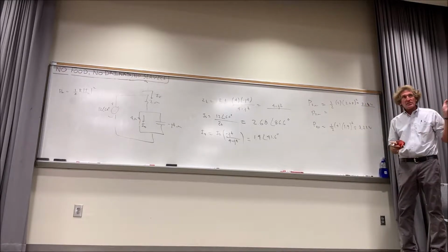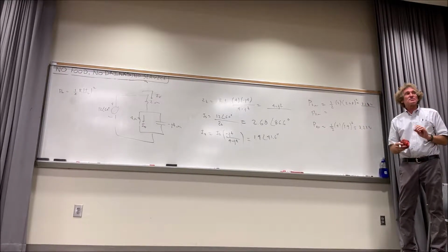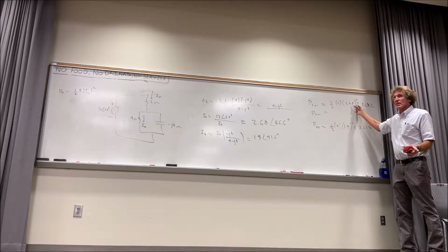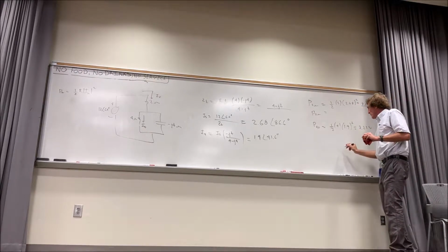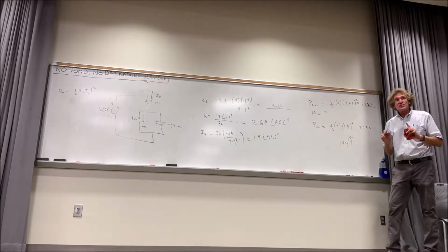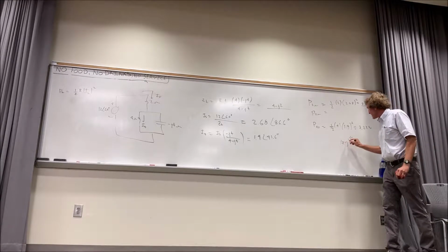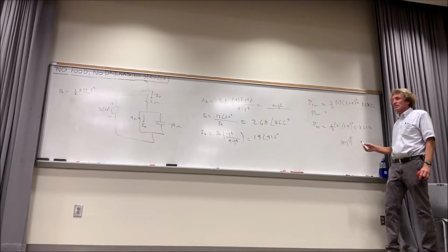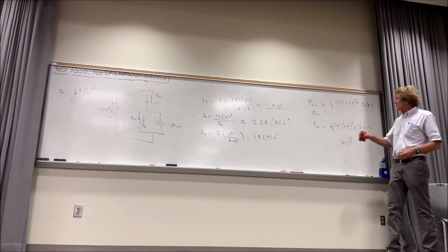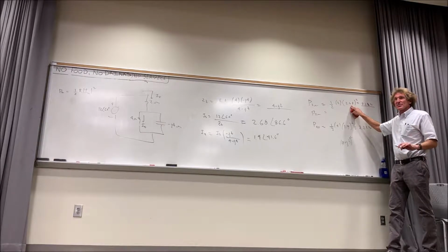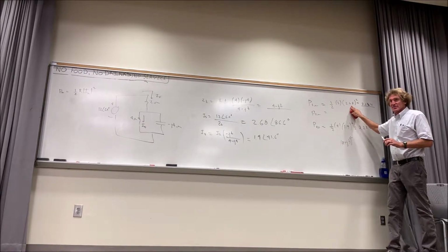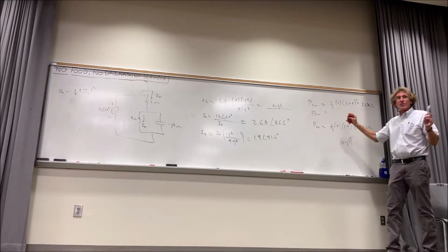Okay. Now, here's something I want you to hear me on. This is a mistake. You know better than this, but it still happens. Where it says I squared, instead of putting the magnitude, people will put a real part plus JB, and square this. That is wrong. It's always the magnitude of the current squared. Magnitude would be the square root of A squared plus B squared. You square that, it's A squared plus B squared. Do you all hear me? So when you put in the value for current to square it, it's just the magnitude that gets squared. Don't put in a real and imaginary value and square it on your calculators, because it'll be the wrong answer, unless you take the magnitude. I'm warning you. Yes, sir.